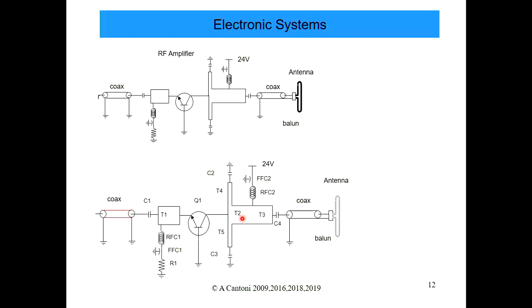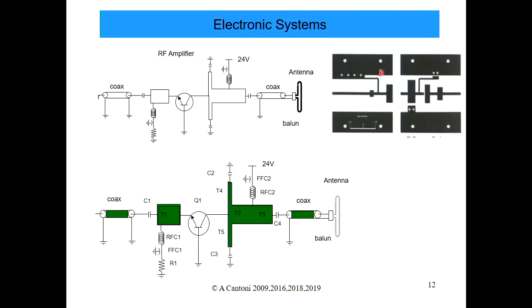Okay, so that's, and perhaps the printed circuit board for that particular circuit looks something like that. You've got these different sections of printed circuit board traces on the top plane that have different widths to form these transformers. We'll look a bit more at transmission lines and how they can look as capacitors and inductors in the future. But they're all not small elements.